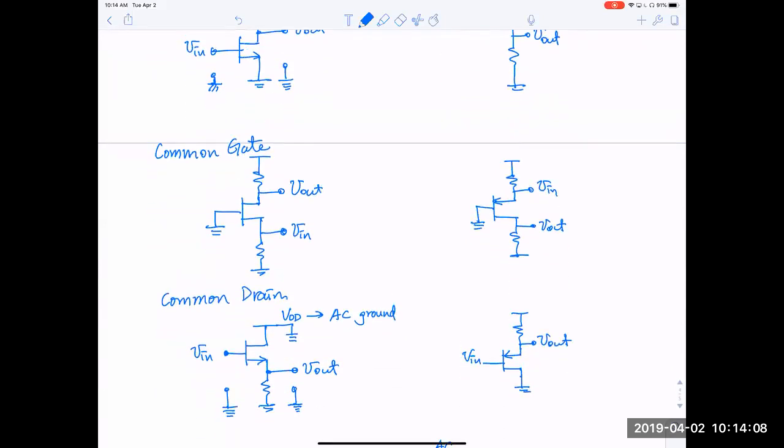Now, the ideal old-fashioned MOSFET is symmetric. Source and drain are really the same. You can change source and drain. But as technology goes, there are source engineering and drain engineering, so source and drain start to look different. In our simple model, the cross-section we draw, they look identical. In more modern transistors, they start to diverge. So we don't commonly switch source and drain.